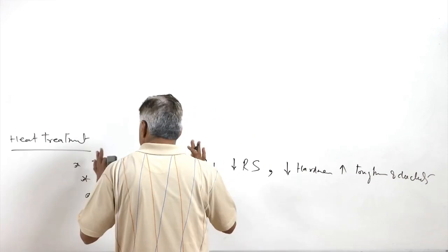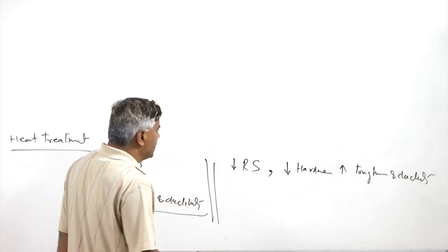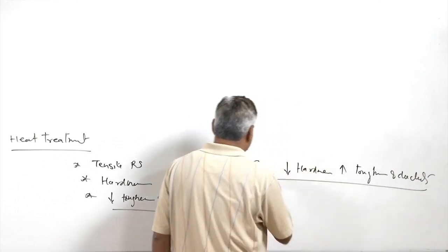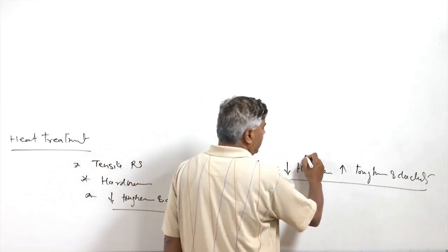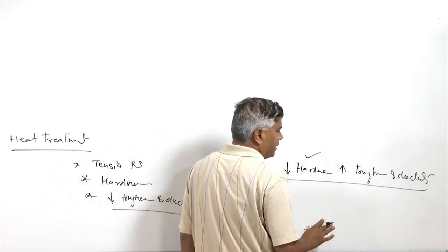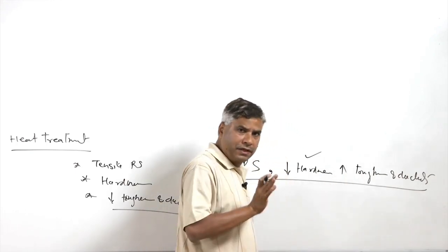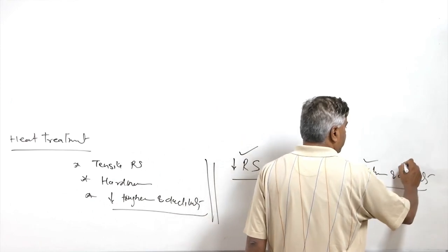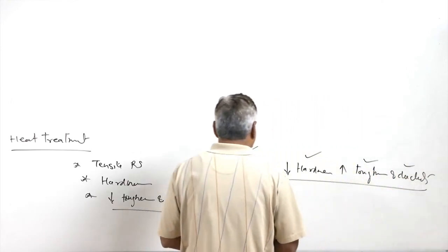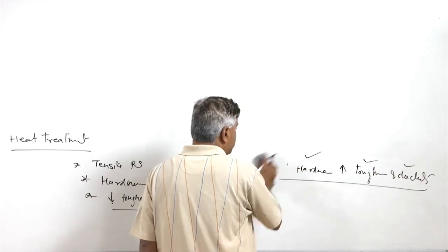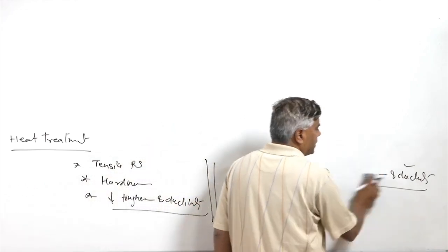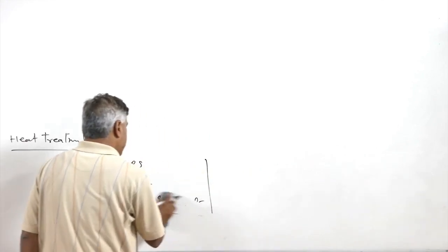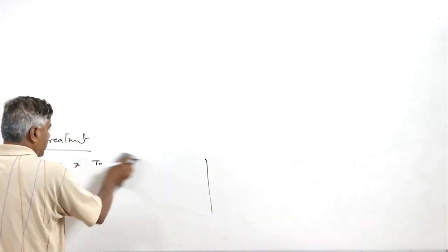So when the steel after the quenching is subjected to the tempering operation, it reduces the residual stresses, marginally reduces the hardness, and marginal reduction in strength is also observed, but at the same time the improvement in toughness and ductility is observed, because hardening leads to the significant reduction in toughness and ductility, which may lead to the abrupt failure of the hardened steel under the impact conditions.